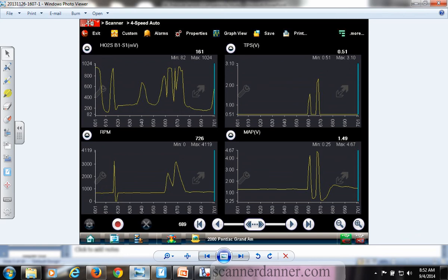Sensor dirty. Good question. Is the sensor dirty? Mass airflow sensors get dirty, MAP sensors do not. Could the sensor be contaminated internally somehow? Of course, but can I do anything about it on a pressure sensor? I cannot. What do you think? What else? Good thought. There's no wrong answer. I promise I won't make fun of you for whatever you say. Robert, any thoughts? You've been on, man.